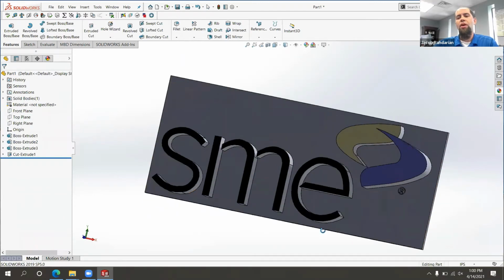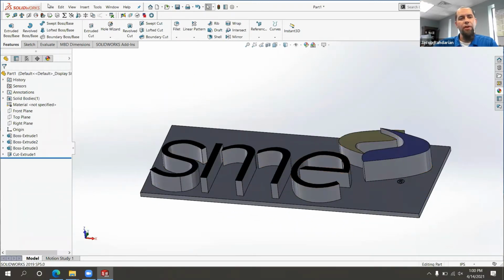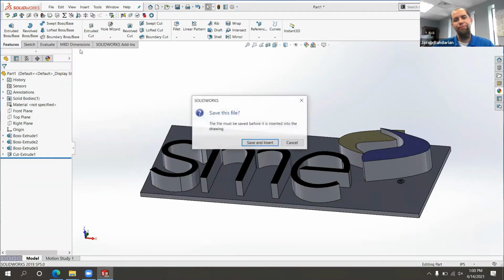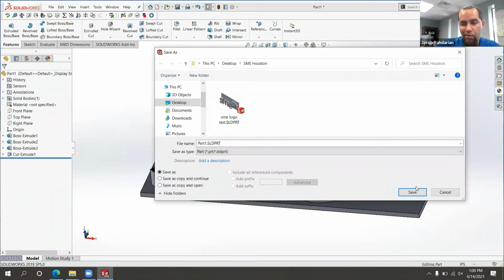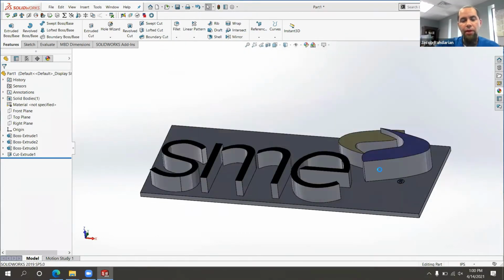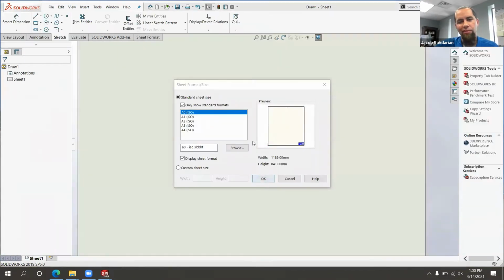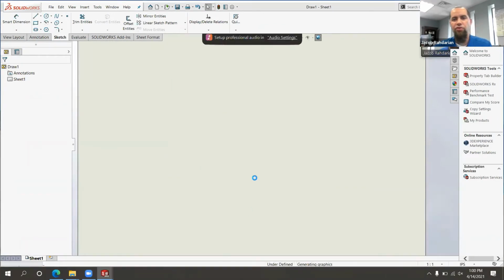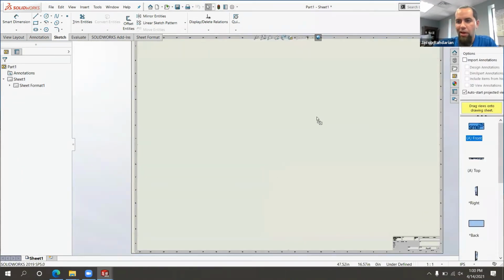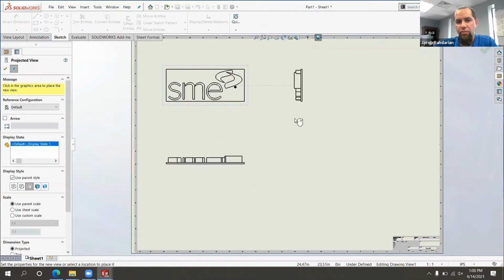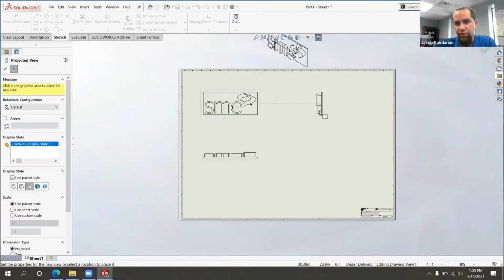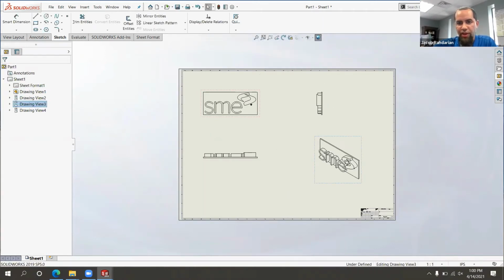Excellent. Before we do, let's go ahead and just show you how powerful and easy creating a drawing from an existing solid model in Mastercam or SolidWorks is. So you simply create drawing from part, as we've done. If you have an established title block or your own drawing format, that's where you would pull it from. You simply grab and go, and it gives you all of the normal orthographic projections. Of course, you could scale them how you need to.